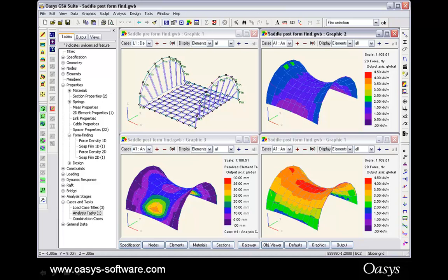Note also that in the bottom right diagram, the stresses in the NX direction are higher than in the NY. This has been arranged so that the warp going between the rings is at a higher pre-stress than the weft going across. This is quite deliberate, and this balance of the pre-stresses affects the final form. Have an equal pre-stress, and the saddle part will be much lower down.